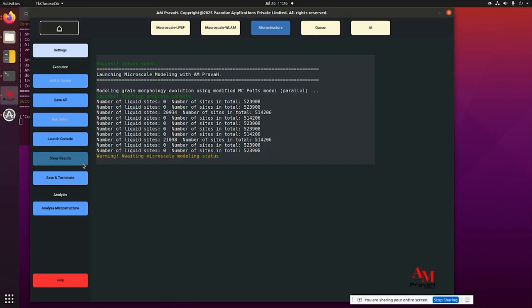Hello, sir. Is my voice audible? Yep, you are audible. Sir, I am on the same page, but there is one thing I would like to raise: in the previous session as well, you didn't consider absorptivity of the laser beam. Yeah, they do. They have different Fresnel coefficients and absorption coefficients that you need to take as an input for the macro scale simulations for LPBF. It is there already. Well, I don't think you have used absorptivity in the case of the Gaussian distribution. No, it is there. You may have missed it.